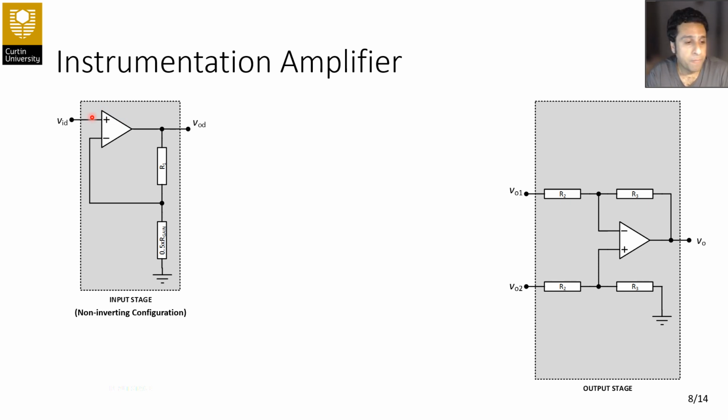terminal or input pin. So let's apply the first rule, that is the equal amount of V plus and V minus, and that causes the reflection of VID because VID is equal to V plus and V plus is equal to V minus. So basically VID will be reflected back on V minus, and you will see VID here on this midpoint. That causes a flow of current here on this resistor, which is half of the R gain, and that makes a current of 2VID over R gain.